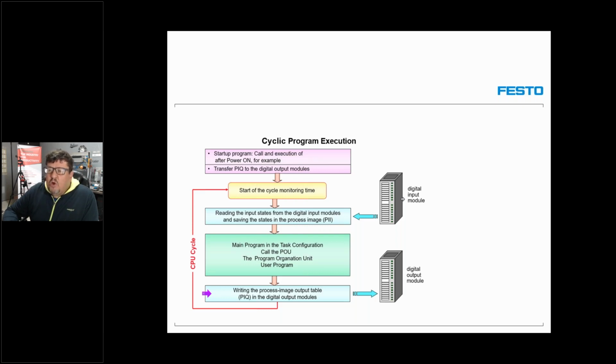That table is like a placeholder for the condition or status of inputs and also the statuses of the outputs. That means when you wire an input like a push button that we did on the previous slide, when that is wired into my PLC and I push the button, that condition becomes a 1 when it is on, or when it is true.